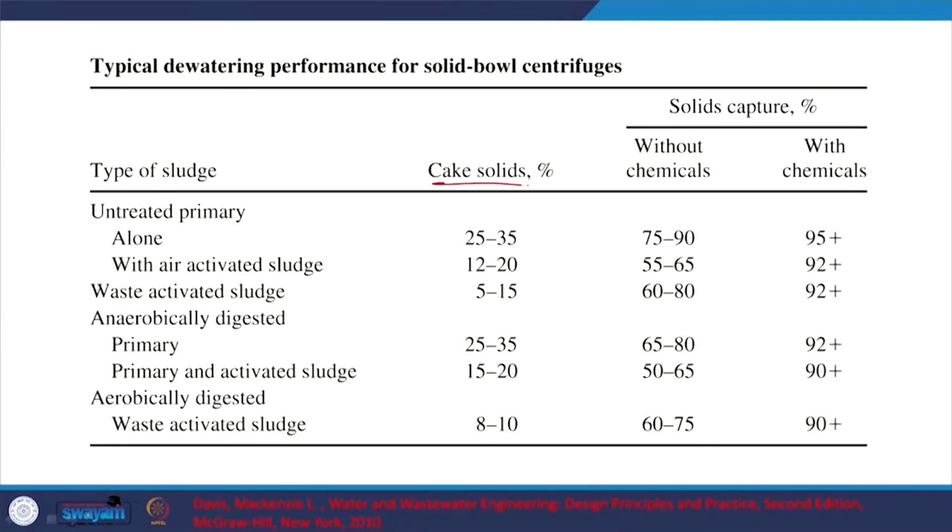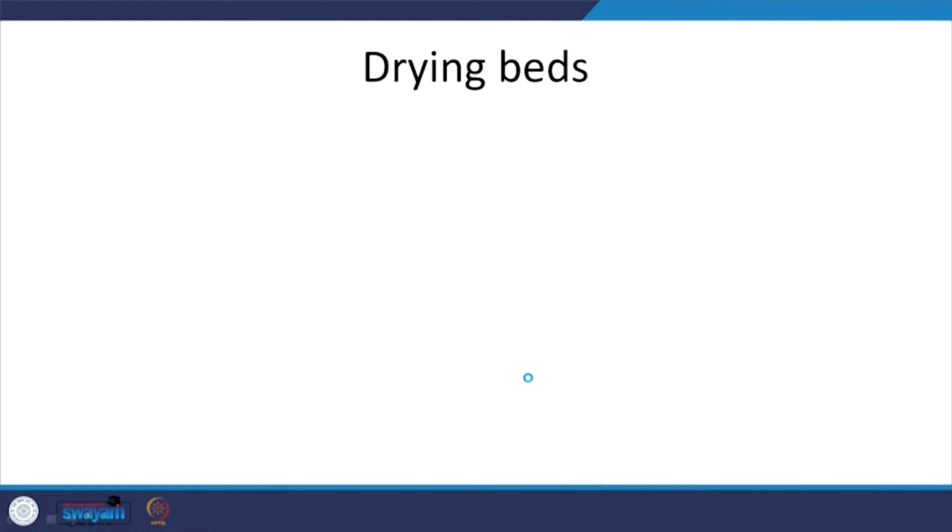Again, the same aspect in the context of cake solids, same as in the anaerobically digested and aerobically digested waste activated sludge. If you see, anaerobically there is relatively better concentration of the solids. That is one aspect to always keep in mind when choosing the kind of stabilization.